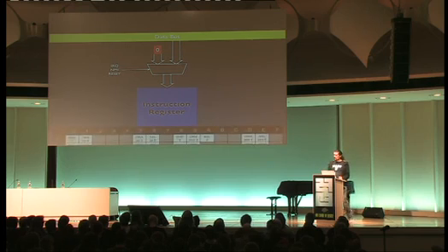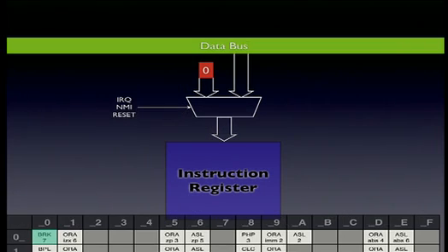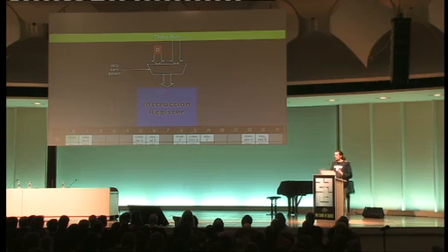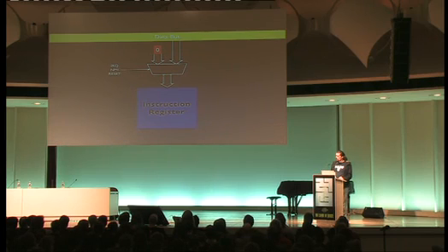And the 0, you might remember, is the break instruction. So this is a really neat trick, injecting a break instruction which does the whole sequence of what's going on, but afterwards it has to clean up and do the right vector and put the break flag properly and everything. So it has to cache that information somewhere, but the sequence is done with break.